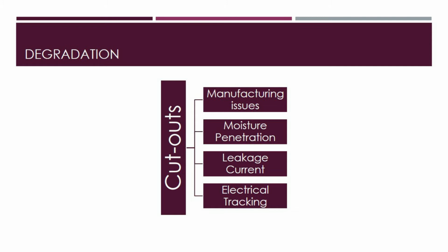Moisture penetration, which in most cases starts at the top insert and progresses into the center hollow, can cause damage to a porcelain cutout. Moisture penetration and freeze-thaw cycles are minimized with the use of appropriate silicone cement and stainless steel inserts. Porcelain is far more fragile than polymer in comparison, and chips can form during transportation and installation, creating failure sites and causing the cutout to fail prematurely.